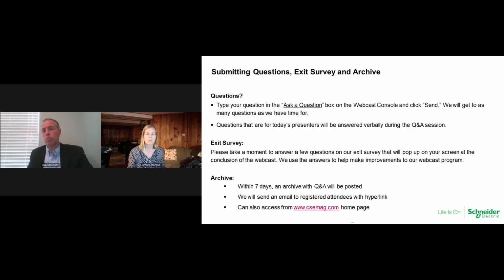And if you think about a failure point in your equipment, your failure point is most likely going to be the incoming cable connection, possibly a bolted bus connection, and the consequences of that failure far outweigh any additional complexity. Now, having said that, we all like the shiny object, and I know people try to push it in. In reality, I like to go with the simplest solution we can, because at the end of the day, the simplest solution is usually the most reliable.